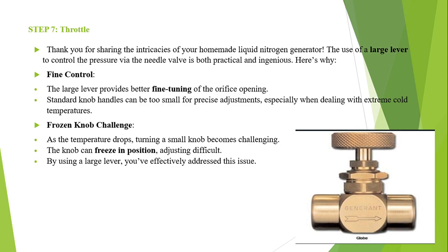Fine control: the large lever provides better fine tuning of the orifice opening. A standard knob handle can be too small for precise adjustment, especially when dealing with extremely cold temperatures. Frozen knob challenge: as the temperature drops, turning a small knob becomes challenging. The knob can freeze in position, making adjustment difficult. By using a large lever, you have effectively addressed this issue.